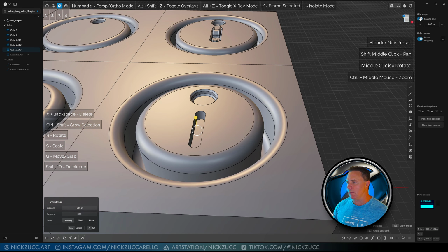Let's create the scenario that we had before where we tap 2, select this. I'm just going to hold down Shift and select these like that. And I'm going to hit Shift D to give myself this new curve. Now I'm going to go ahead and select it, and I'm going to tap the period key to isolate everything like that. And now we're back to that situation where if I tap 1, if I select this, so if I tap B, if I want to go try to fillet that, it's going to fail on me. Okay.